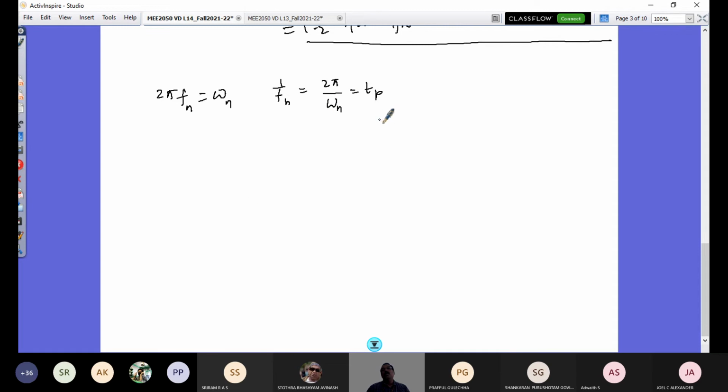So when you have two equivalent dynamic masses at front and rear, MSF and MSR respectively, what is the advantage? They are going to act as two independent single degree of freedom system models. Two masses: the front axle is going to vibrate as a single degree of freedom, and the rear axle, when it is excited, is going to vibrate as a single degree of freedom system. But what is to be noted here is that first the disturbance comes on the front axle and it is set in vibration. Then it is going to excite the rear axle also, and that is going to vibrate.